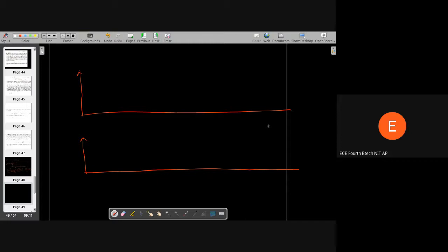Mel filter bank, I will convert into our analog scale. Okay, I'll represent all of this in analog scale. I know digital frequency is minus pi to pi, but we talked earlier, in revisiting our digital signal processing basics, about how we represent omega equal to omega ts. This is analog, so it is easy to visualize and understand things in terms of analog frequency. Even though we are dealing with digital signals, when we visualize them, we take the axis in terms of analog frequency. We have talked about all this anyhow.